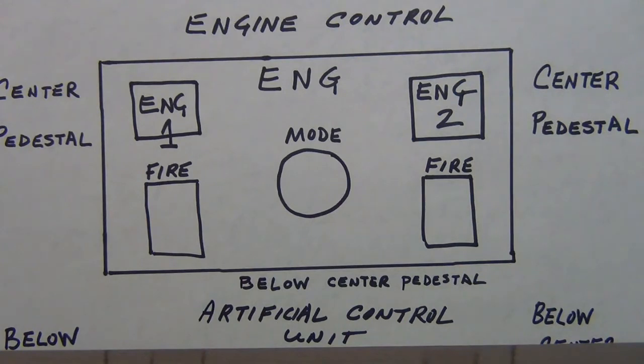Here are your 2 options. Number 1, ignition start, wet start and normal mode. Or number 2, normal mode, dry cranking, and ignition start. You're right, it's the last option. Normal mode, dry cranking, I mentioned dry crank, and ignition start. So that gives you an idea. We're going to come back to our test questions in just a bit. But let's see what happens here.